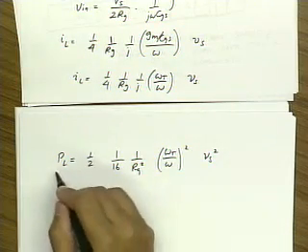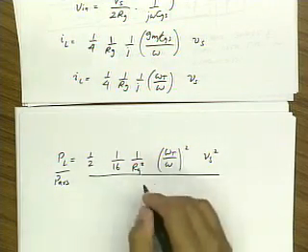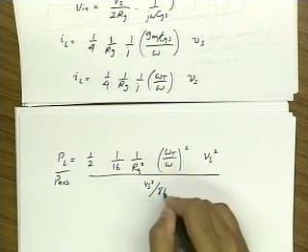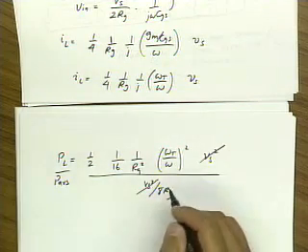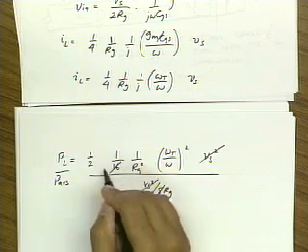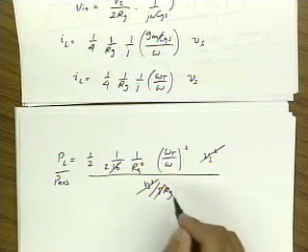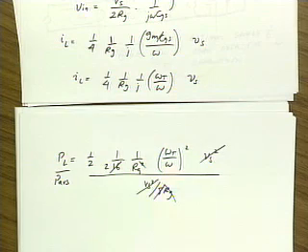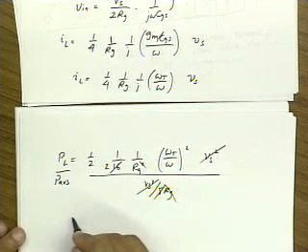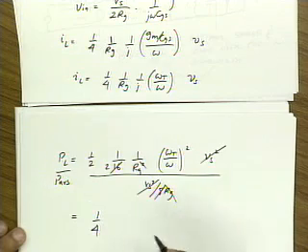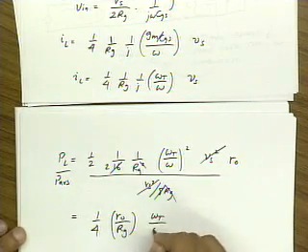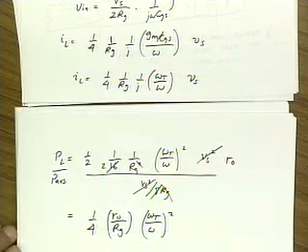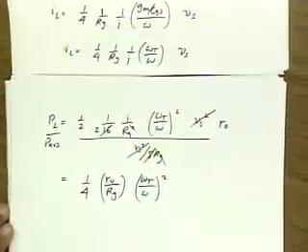And if I now divide this by power available from the source, that's Vs squared over 8Rg, and so the Vs squared cancels out. This 8 cancels out with this, and I get a factor of 2 here. This Rg cancels out with this Rg. And so my final expression looks like 1/4. Oh, and I forgot to multiply by Ro here. 1/4 Ro over Rg, omega t over omega squared. If I made a mistake, maybe you guys can catch it.